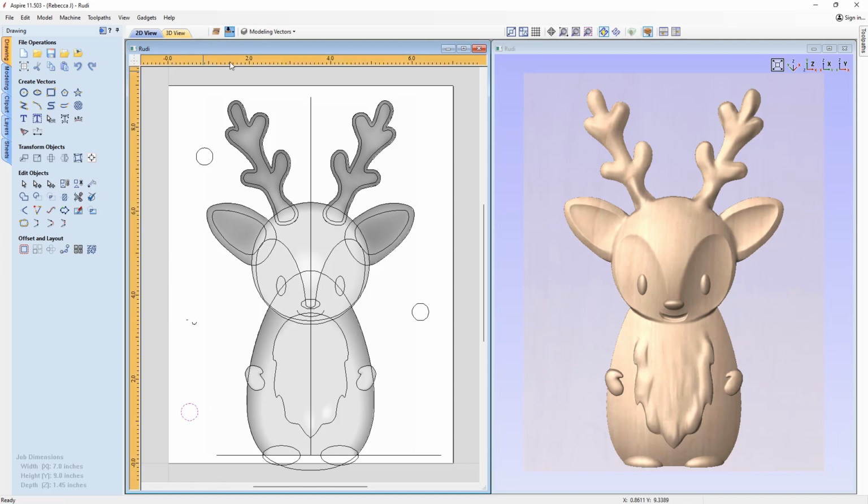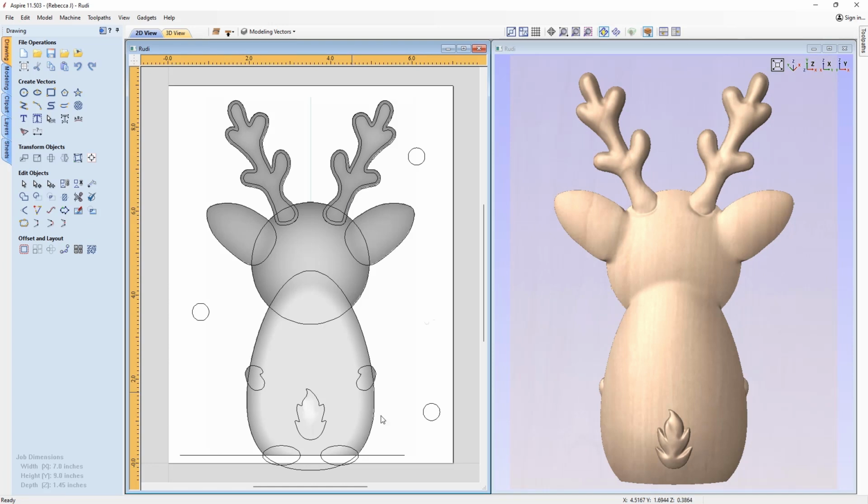And then on the bottom side, where we've copied those vectors over, we're going to be machining the dowels for the bottom side directly into our spoil board so that the two align perfectly. And by doing this in an asymmetrical fashion, it also ensures that there's only one possible way for us to actually flip our material over, so we don't have the confusion or the mistake of flipping it in the wrong direction.